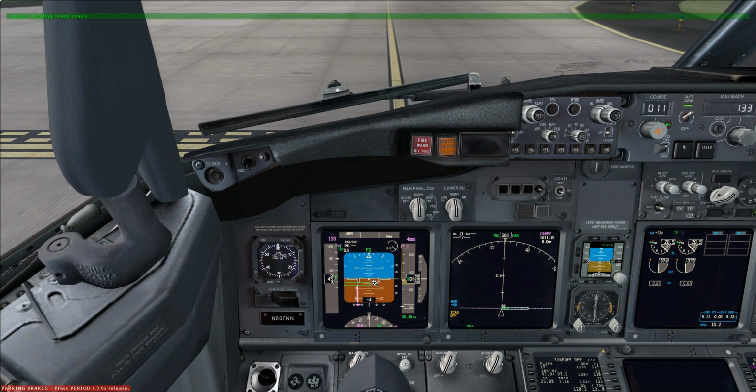And if you're going to stay on the autopilot, you press either toggle switch again, verify TOGA mode is enunciated on the FMA, the flight mode annunciator, this is up here. Verify the thrust advances to go-around, retract the speed brakes, and you monitor the system performance.